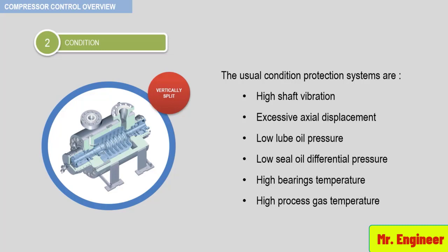Most condition protection systems require a 2 out of 3 vote to permit shutdown of the compressor unit. This is to prevent shutdowns of the compressor resulting from instrument failure. In these systems, all condition protection devices must be supplied in triplicate. The one exception is usually shaft vibration, since the level of shaft vibration varies around the orbit of the shaft in the bearing.